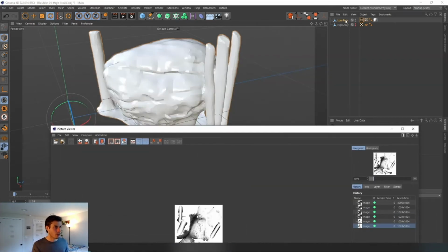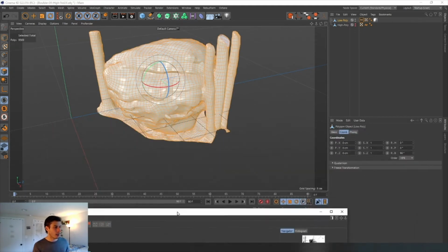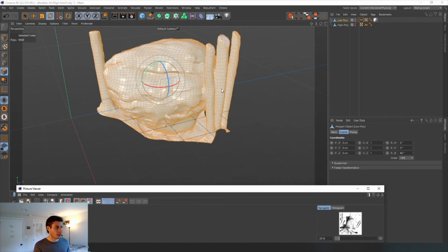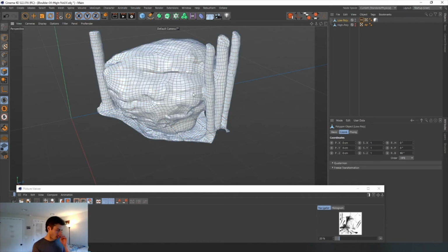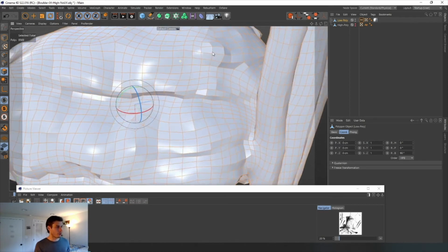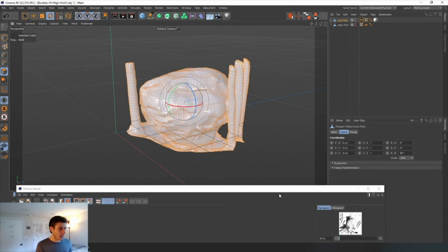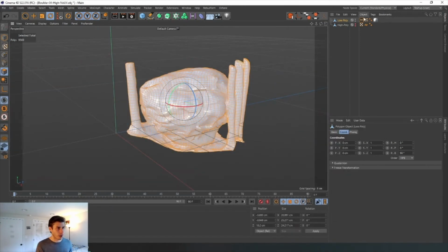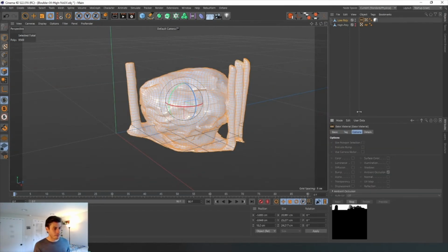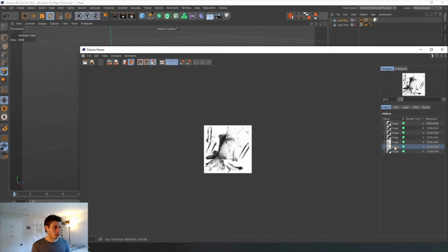One thing that might happen is sometimes your photogrammetry software will bring in all of your geometry like this, where your normals are facing inward. So your normals are the wrong way. I'll just give you an example of what happens when you bake. You'll end up with this really dark ambient occlusion, which doesn't make any sense. It's basically reversed from what you're looking for. And the reason it's doing that is because your normals are reversed.